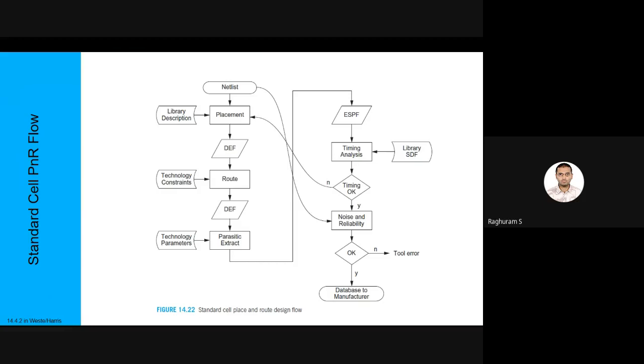Like that, in our VLSI design also, we don't want resistance or capacitance anywhere because they tend to delay the circuit operation. But because of the circuit structure, the material properties and nature of the fabrication, etc., these resistance and capacitance elements automatically are formed in the circuit. So that's why they're called parasitics.